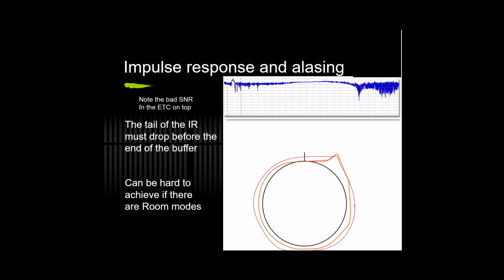The second reason for minimizing the room mode is that you can often get a very bad signal to noise ratio in the sub region, so you will be unable to find your subs in your measurements, and therefore unable to make the alignment of the subs. You can see this in this graph. It's an impulse time graph, and you see here a lot of ringing, which continues all the way.